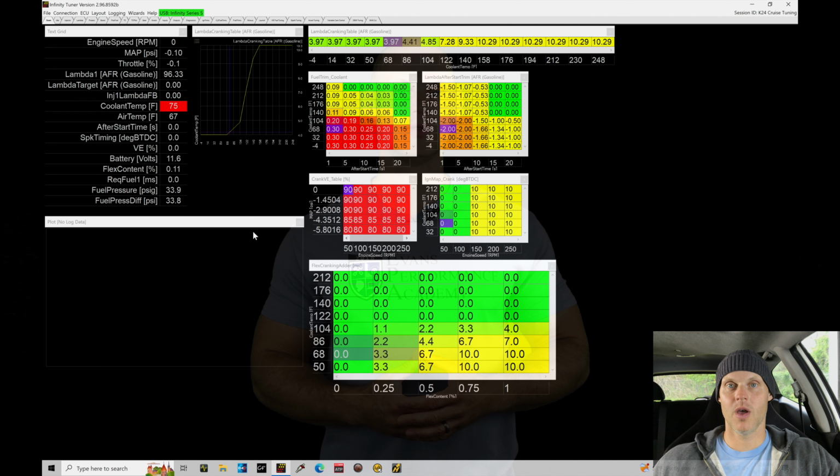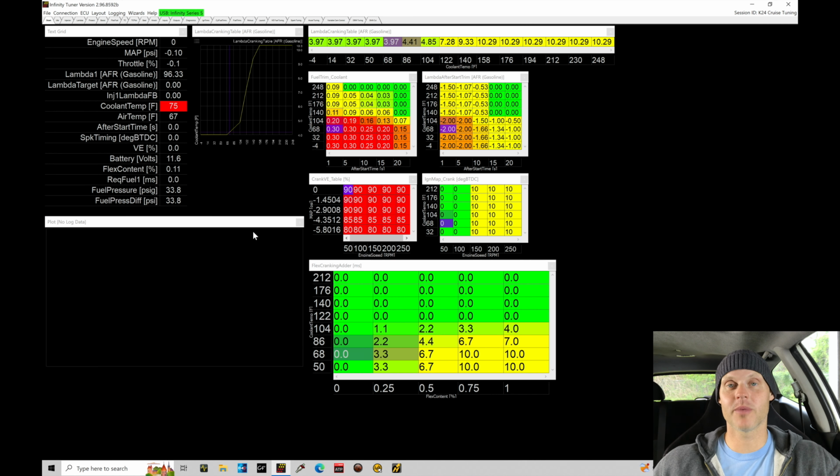Welcome back to our live training session here. We're going to be taking a look in this video at getting the engine to fire up and run and dial in our idle. We're also going to be checking our trigger sync between our Infinity and our engine, verifying with a timing light that the timing as we command it from the Infinity is going to match what we have at the engine. So we have a lot of things to cover and unpack here.